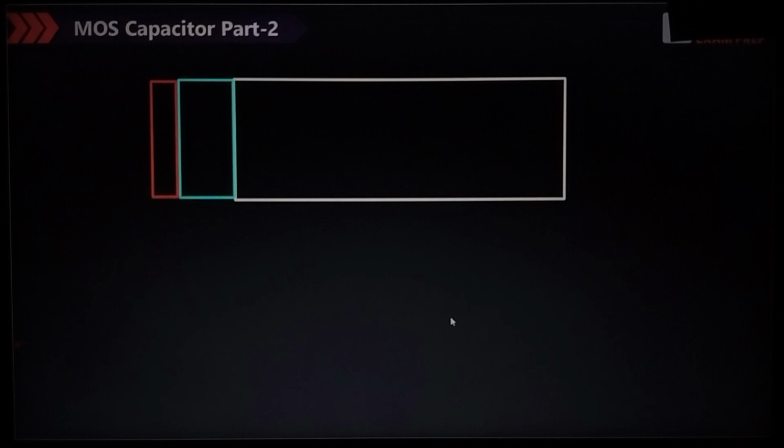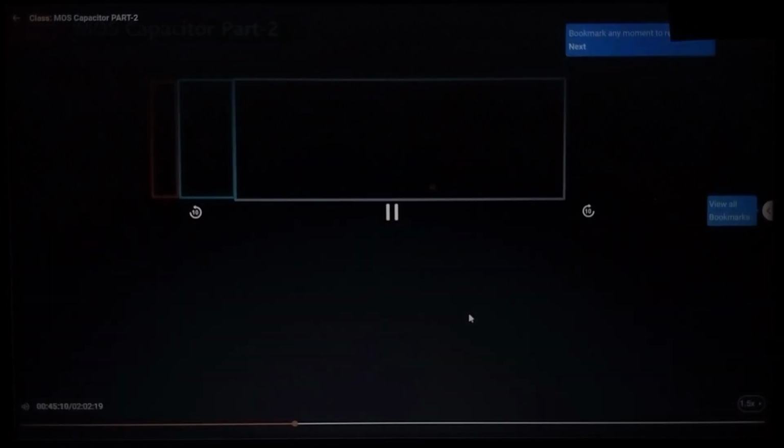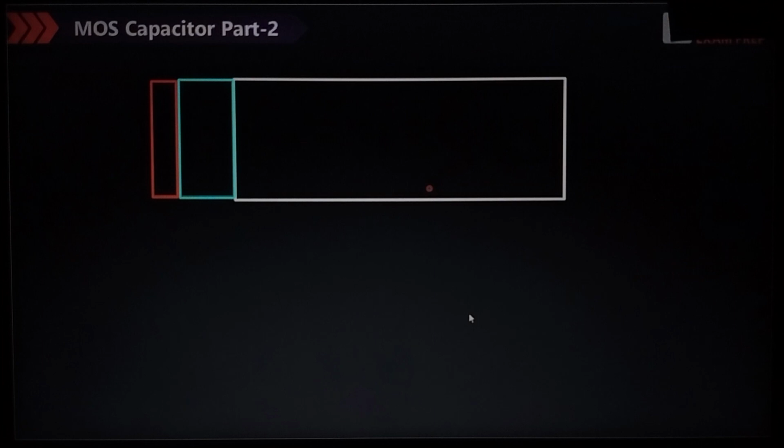We are not adding contamination there. Contamination is always there, we don't want it. Sometimes it will support, sometimes it will not, and it is very dangerous also. Everywhere impurity is present, and that's why IC fabrication is not so easy a task. Now we are going to start. Na ions will be present at the back side, no problem. What about the Na ions? Na ions are immobile charge carriers, and that's why they will not help in conduction.